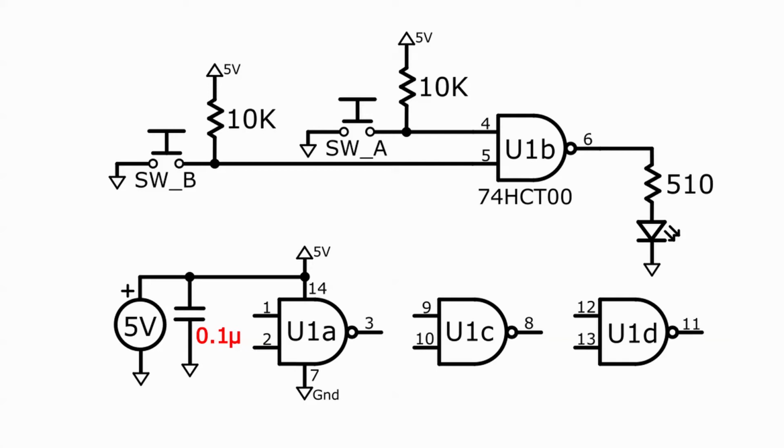Secondly, I'm going to eliminate all floating inputs. A floating input is an input pin which is not connected to anything. As things stand, there are 6 floating inputs in the circuit. Think back to the truth table for a minute. An input to the NAND function has 2 possible values, high or low. There's no third choice. There is no unknown or not connected. Many circuits act unpredictably if they don't have definite input voltages.